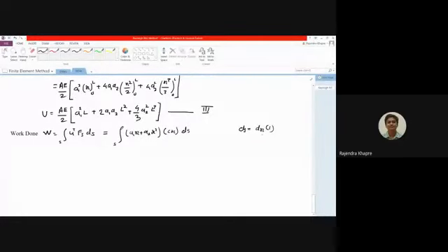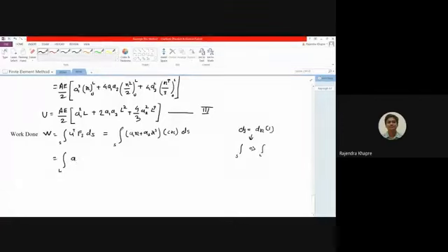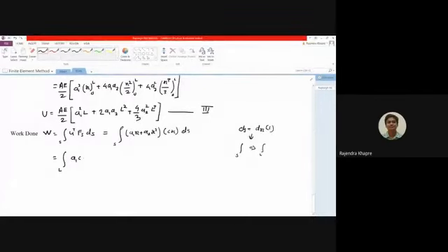So this we have already seen, and if you use this, your integration over the surface will now become integration over the length, because the circumference portion we are considering as unity, that is 1. So the same expression can now be written as integration over the length. If you go for the multiplication of these terms, this will be a1 into c into x squared, plus we have a2 into c into x to the power 3, and this will be integrated over the length now.